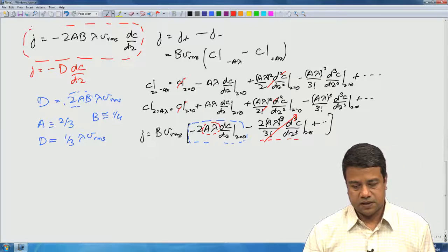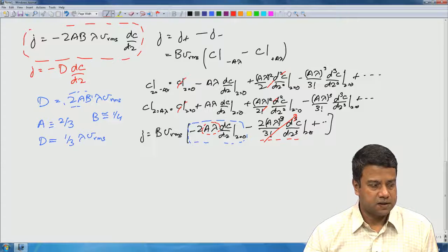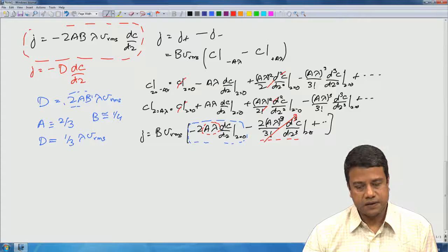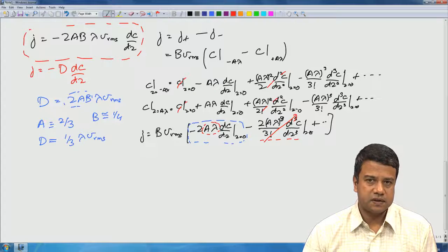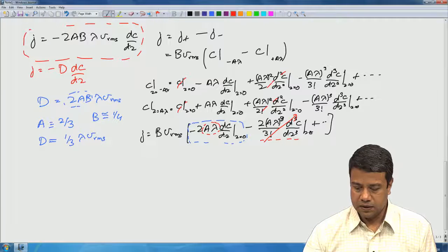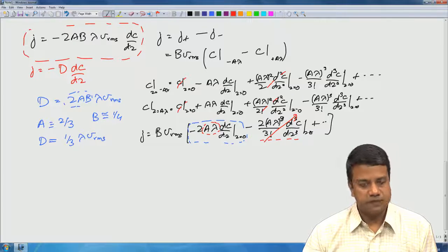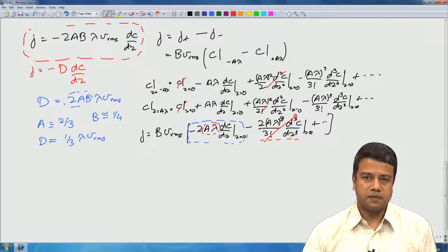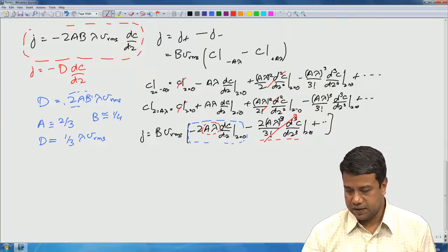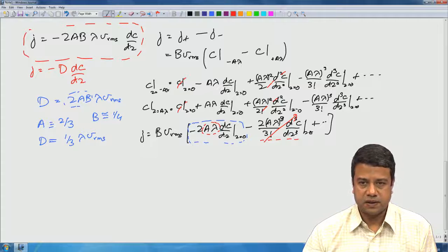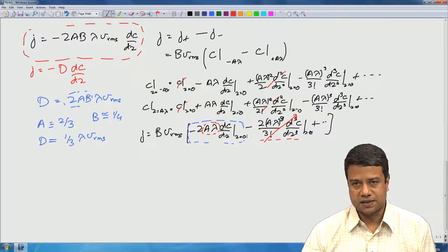Okay. And just by comparing that with the standard Fick's law for mass transfer, you can see that the diffusion coefficient is proportional to the mean free path times the fluctuating velocity. So, therefore, if we know what is the mean free path and what is the fluctuating velocity, we can get some estimate for the mass diffusion coefficient. So, we will next try to calculate what are the mean free path and the fluctuating velocity in gas molecules, in gases. Okay.